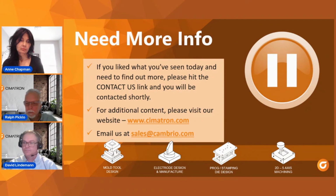Alex was asking the same thing. Do you need post modifications to import the probing measurements back into the Cimatron? No. You don't need post modifications to bring the report back in. There is some customization that we do for you once you get this to format the report, because every control has a different style of report, and then we have to format it to bring it right back into Cimatron. That is, reading that back in is part of the in-process measuring and on-machine inspection software. So that's how that works there.